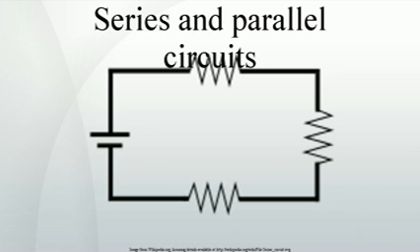For a larger number of coils, the total combined inductance is given by the sum of all mutual inductances between the various coils, including the mutual inductance of each given coil with itself, which we term self-inductance or simply inductance. For 3 coils, there are 6 mutual inductances and there are also the 3 self-inductances of the 3 coils. Therefore, by reciprocity, the last 2 groups can be combined.